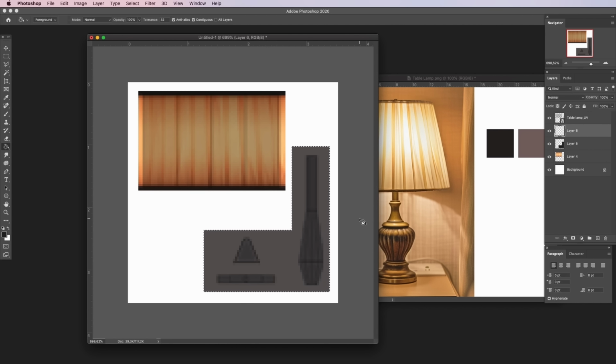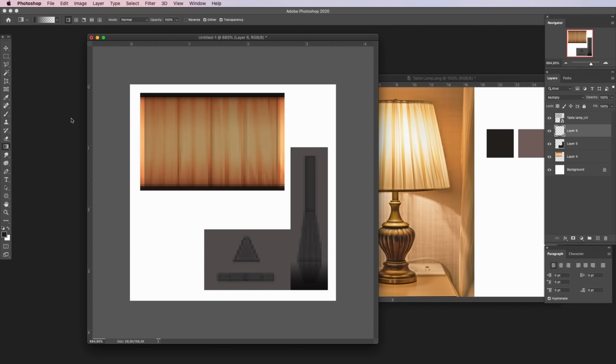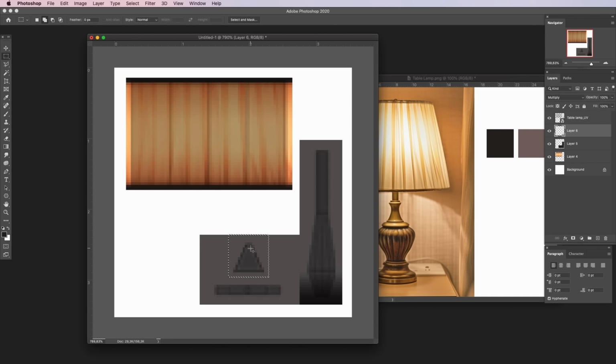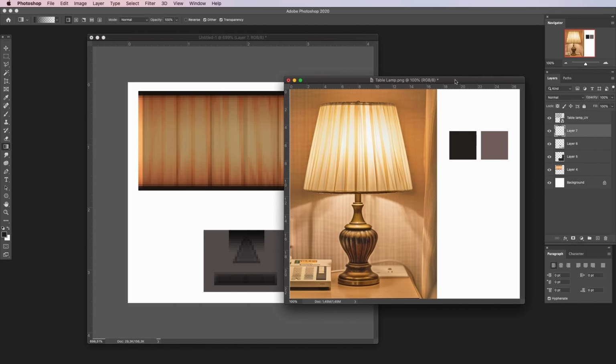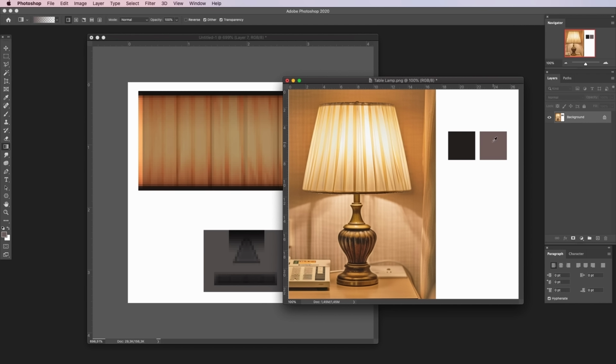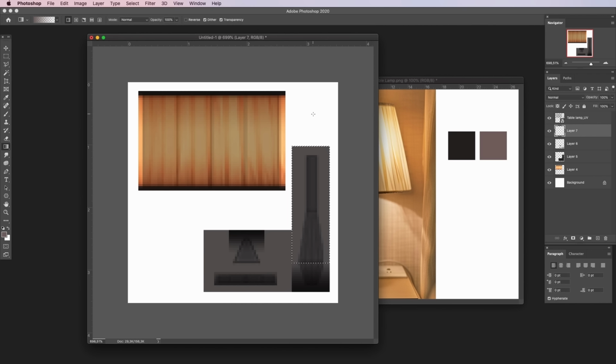Create another layer and change the blend mode to multiply. Now, using the selection tool and gradient tool, I will add some shadows. Here it's important to understand which parts of the UV correspond to the location on the model, in order to draw in the right places. Then I will create another layer and make a gradient with the second color example, to simulate the light from a lamp.